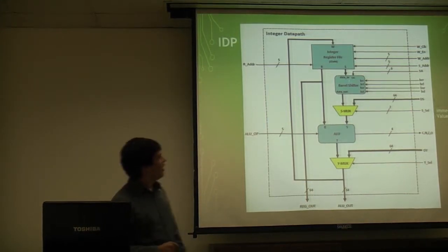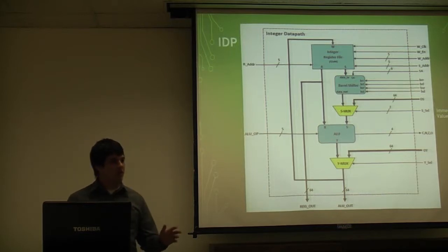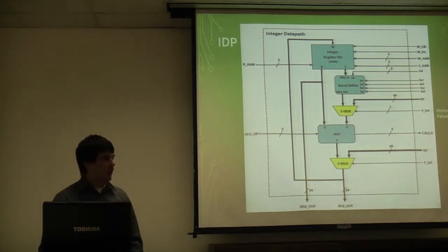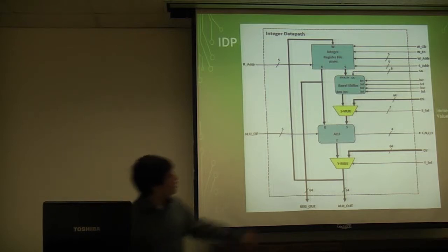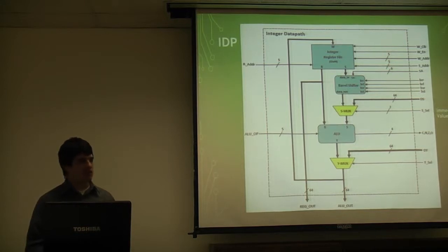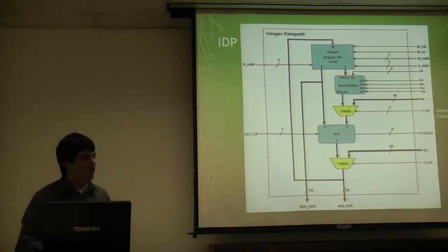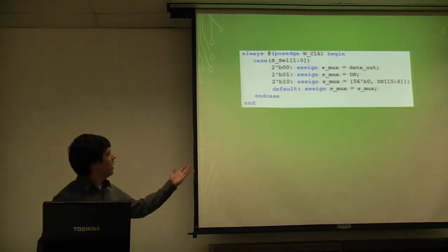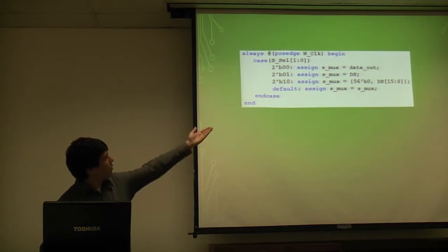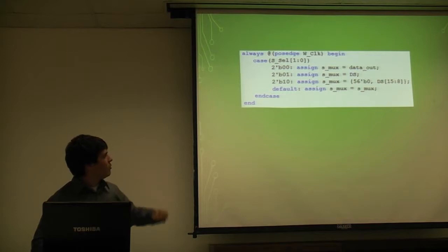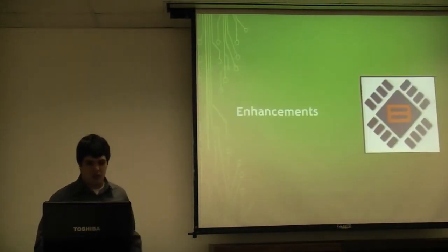amazing barrel shifter. It's the only thing I'm really going to tell you about it right now, so we're going to get into more detail later, is that it passes S as its default, and it'll perform all the amazing operations later. We also did have to expand S-select, though, to account for the 8-bit immediate instructions, such as subtract immediate, add immediate, etc. And this is our S-select. As I mentioned, it will receive either S, which is that out from the barrel shifter, the DS, or the 8-bit immediate, and its default stays the same.